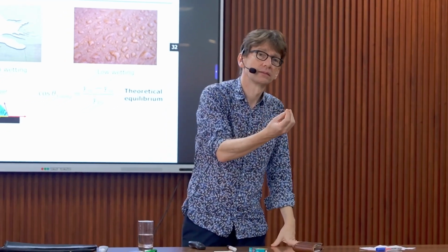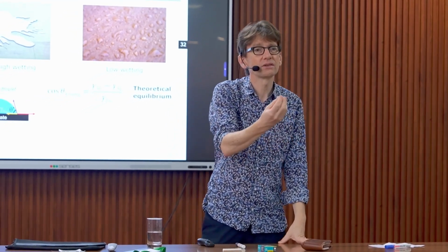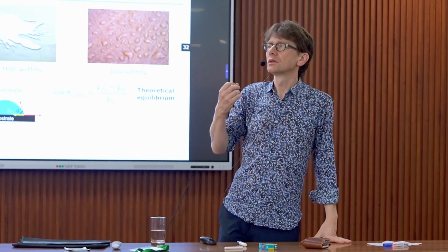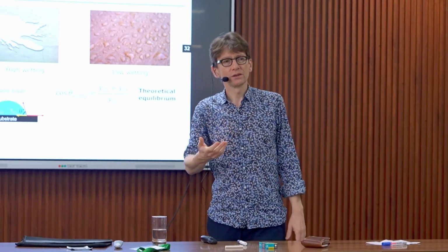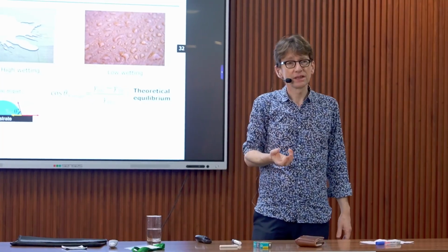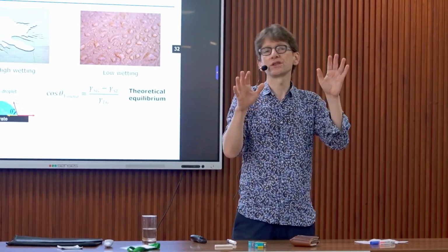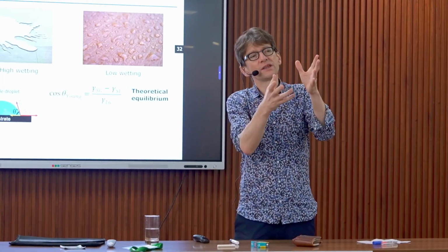But you cannot do that because you have a magnet. You have an additional force. So you cannot say that your droplet is just following the Laplace equation under gravity. There is an additional force, but the machine doesn't know there is a magnet. So the machine says surface tension decreased because the droplet changes shape.